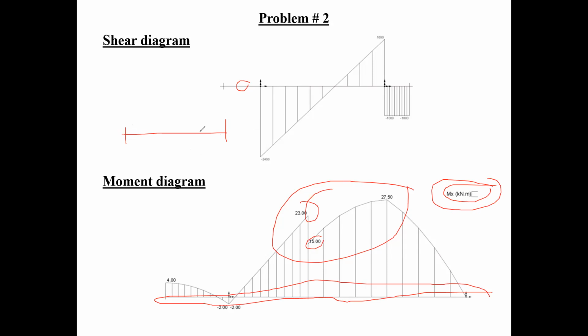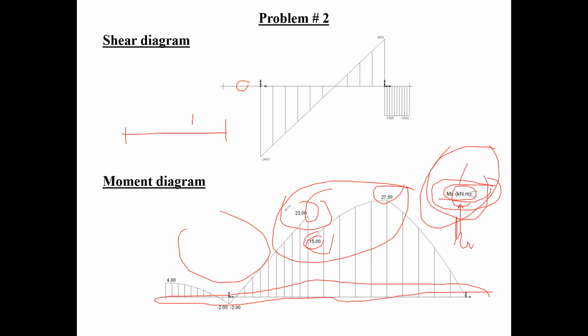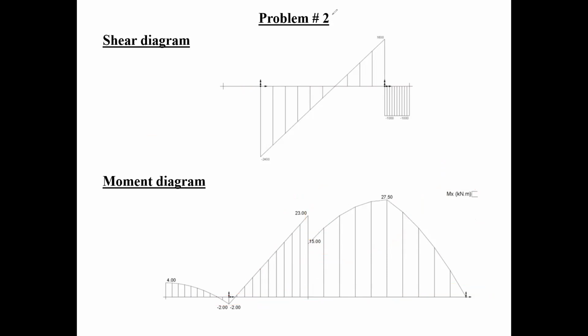When he sent me the email, I told him, always look at the values here. In ADA, it will always tell you what units the values in this table are in. So make sure that it's in kilonewton meters. If it's in kip foot, ADA will tell you. That's why it's very important that somewhere on your diagram, somebody knows whether this is 23 kip foot or 23 kilonewton meter. The units to me, guys, are the most important things in these problems. If the units are wrong, then it's wrong as far as I'm concerned.